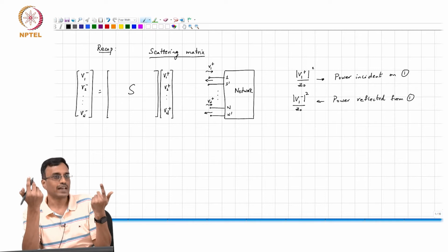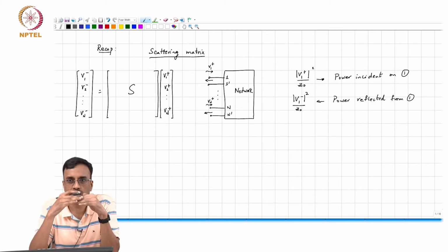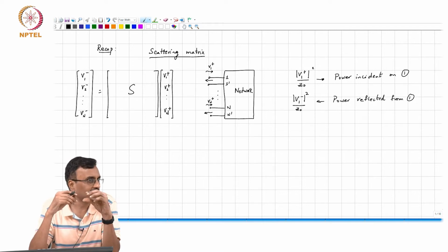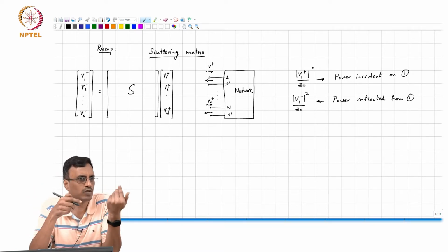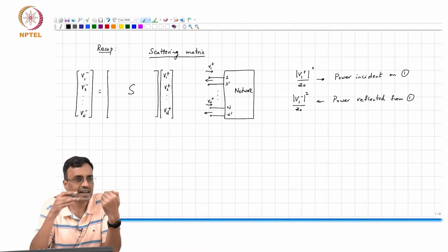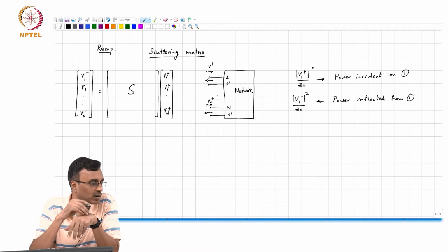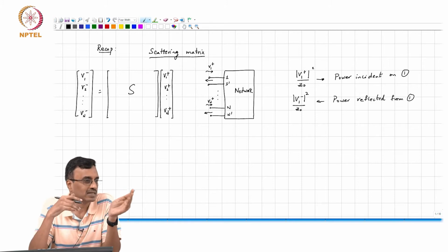You should expect that as the terminating impedance gets closer and closer to the characteristic impedance of the line, the reflection coefficient becomes closer and closer to 0. The impedance does change over the length of the cable, and at the other end of the line it will no longer be equal to Z0.